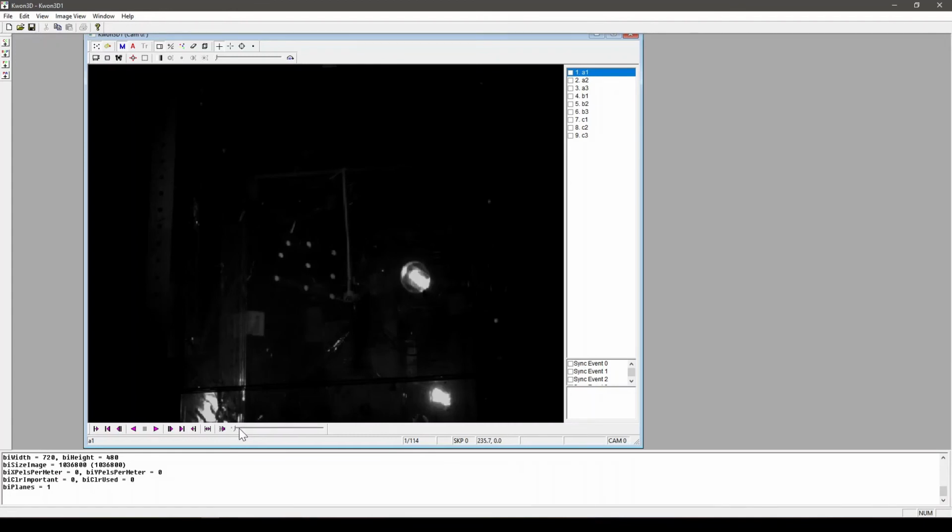If I click here, now we have selected at frame 0, so we have selected 9 points. If I again click here, it will automatically change to frame 5. But when the stroke reversal is happening, remember this point, very important: when the stroke reversal is happening, make sure you select frame by frame, one by one.